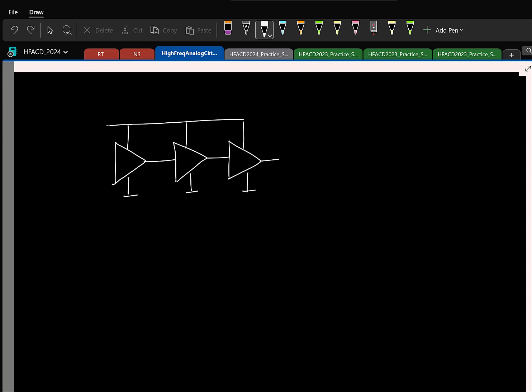So firstly, let us say we have a system that is formed like this, wherein we have multiple small blocks making a bigger system. Here each of them is not an op-amp as such, it is some circuit made using an op-amp, right? And the op-amp, as we know, has a single-ended output, so it takes one wire for processing the signal. As you know, each block will have its own ground and supply, and let's say all of these will have the same supply. So this is connected like this, and outside the chip you will go and connect it to a power supply like this.